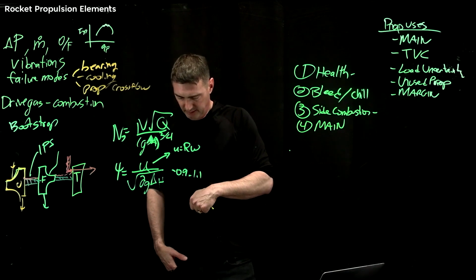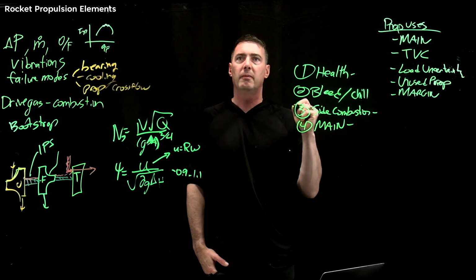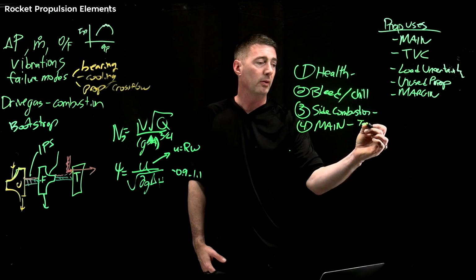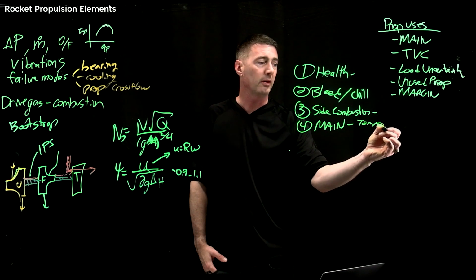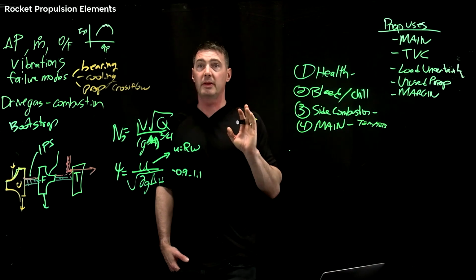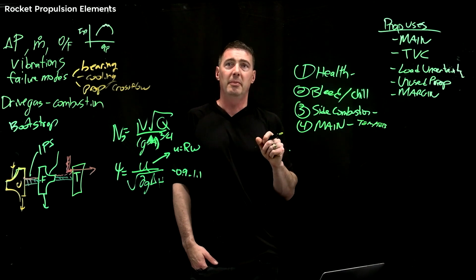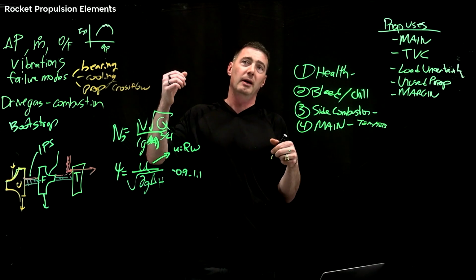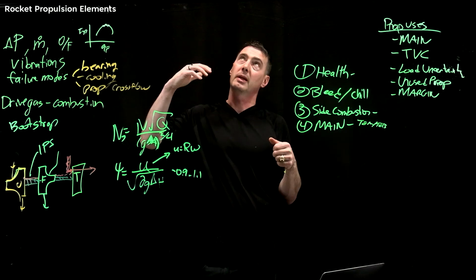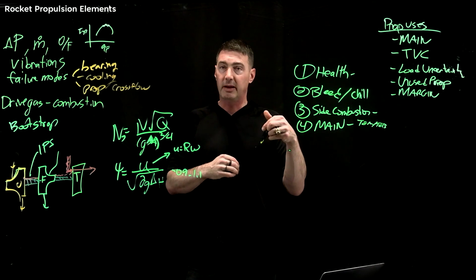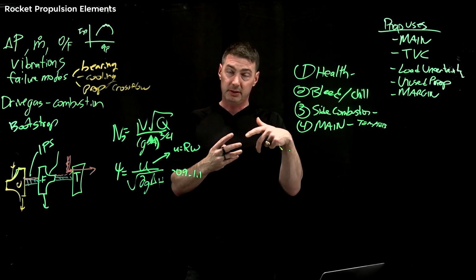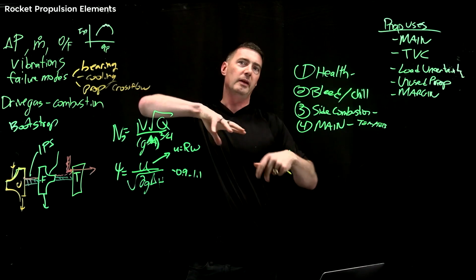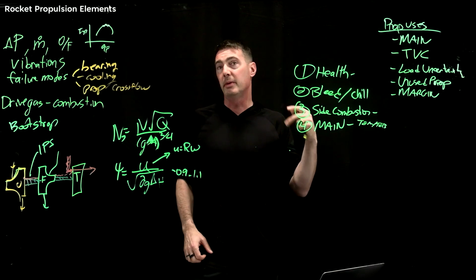And from an ignition point of view, at Virgin Orbit we used TTEB, and I know SpaceX did that a lot on their Falcon 9. I'm not sure what they use for the Raptor engine, but it's sort of a secondary reaction that absolutely burns. So in fact, if I remember correctly, we would drop LOX, and then you would hit it with TTEB, and so you actually get LOX TTEB combustion, because TTEB basically immediately goes, and then you would transition to fuel, and then turn off your TTEB. That's how we would step our way up.